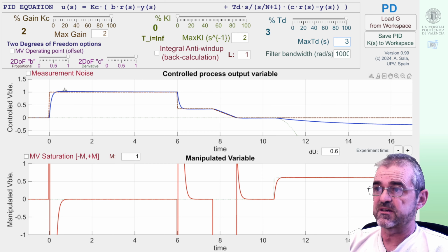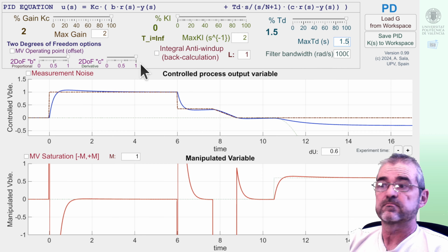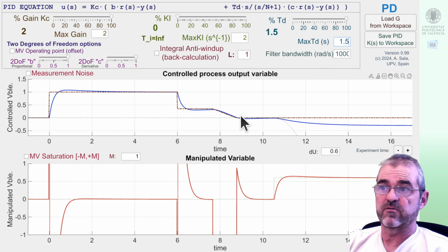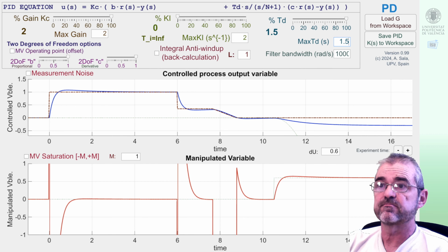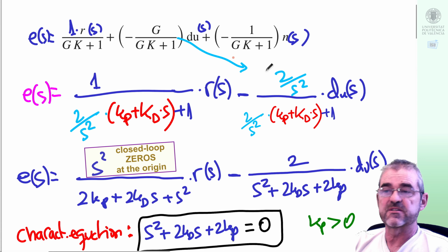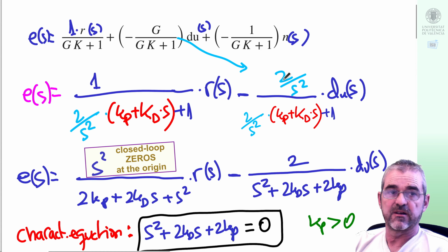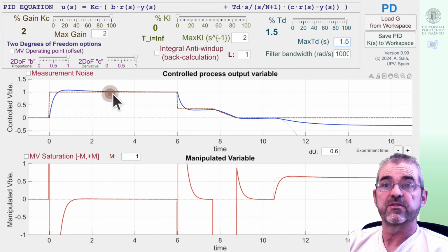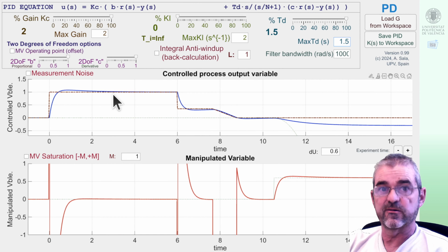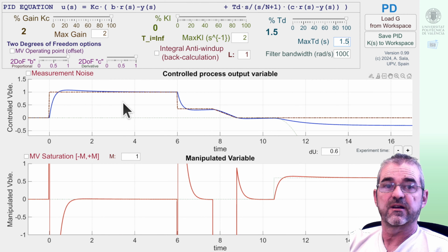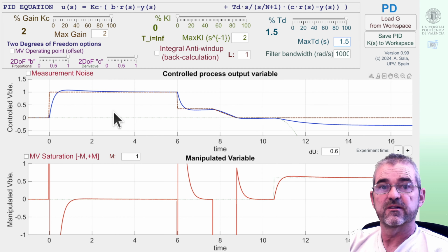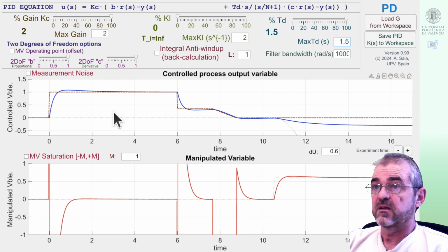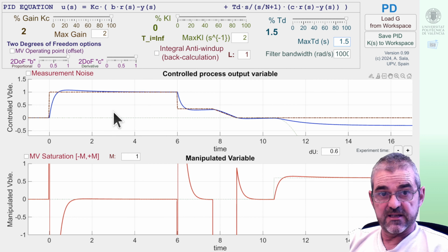Note that there is still a bit of overshoot, because apart from the poles of the transfer function, we have some zeros. Then I can go to one side of the set point and go back, but this is a non-oscillatory overshoot in the sense that it will never cross the set point line again downwards, whereas oscillatory overshoots continuously cross up and down. Then we will conclude with this.